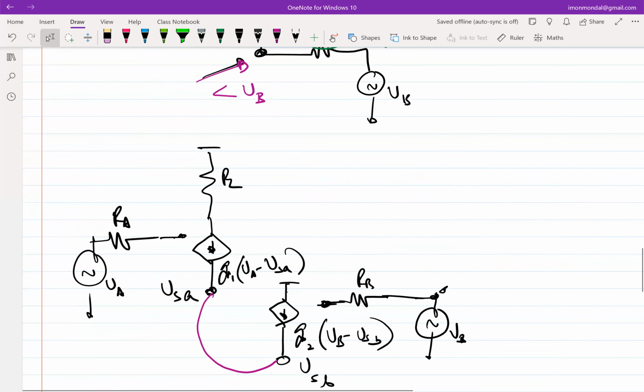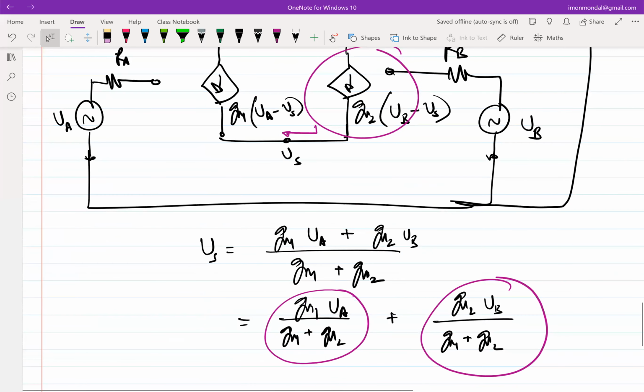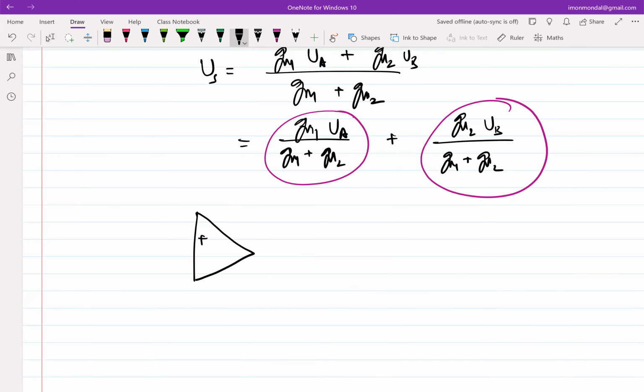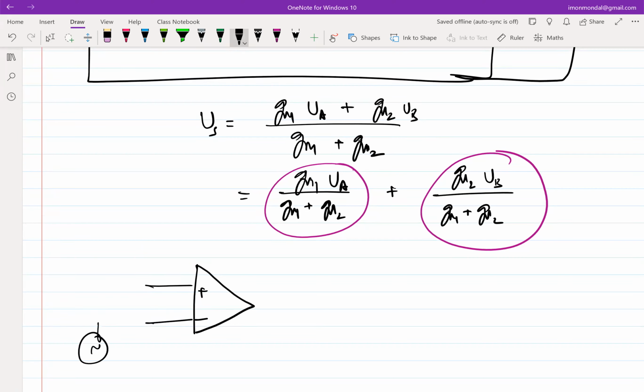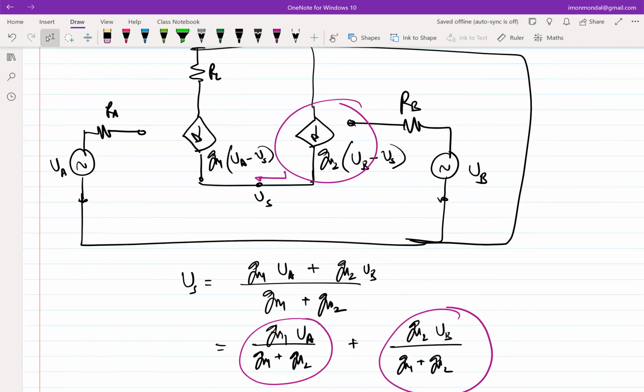But in case of an op amp, since we are trying to get an op amp into our picture, one of the requirements is that both the terminals are identical. Not only that the input impedances are identical, you might want to connect the input here, or you might want to connect the input there, or you might want to swap places also. So essentially, what that boils down to is symmetry. More often than not, we would want the two incremental transistors to behave like they are identical, which means that we want both the GMs to be identical.